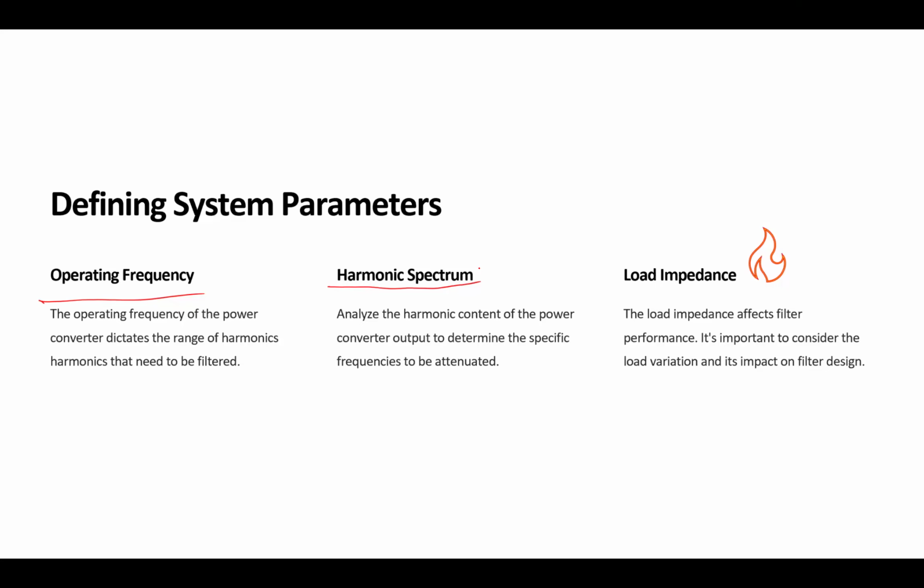Practically, it's not so. Practically, we don't have the ideal case. We have inner harmonics, and some reflections of something happening between 60 and 180, and even below 60. There is something happening, but ideally the harmonic spectrum starts from 180. That gives you a good idea of where the cutoff frequency should be designed.